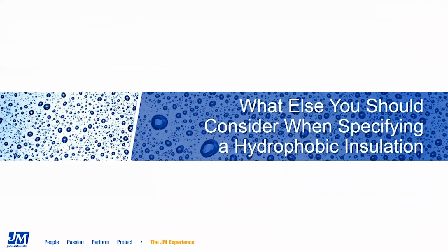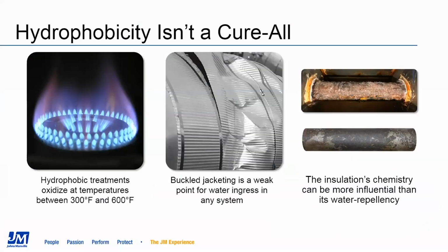Well, let's take a look at other things to consider when specifying insulations and how hydrophobicity should be factored into that decision. Hydrophobicity alone is not the cure-all to CUI, especially in cyclic high temperature situations. That's where hydrophobicity is less effective.